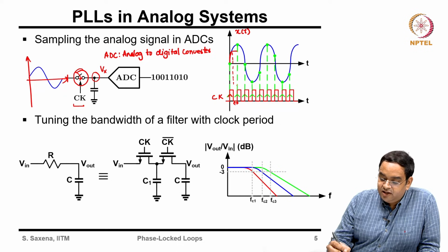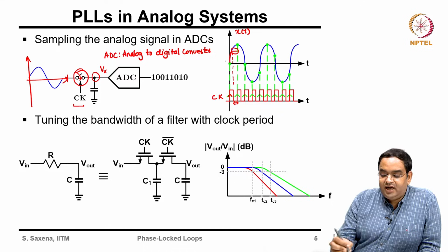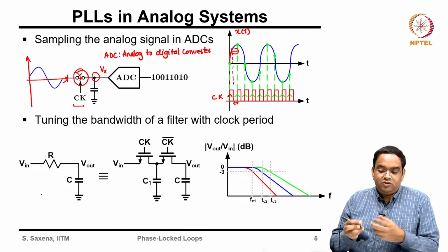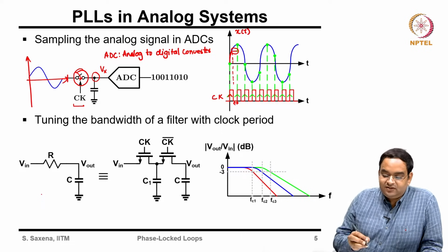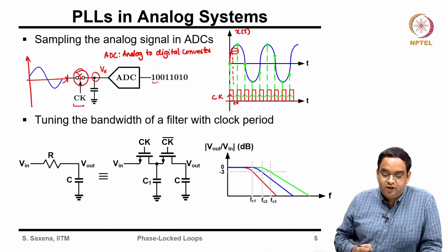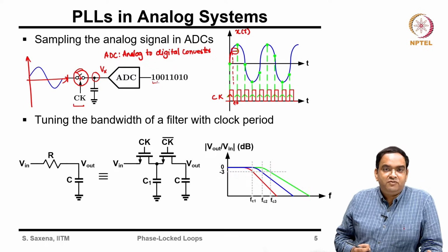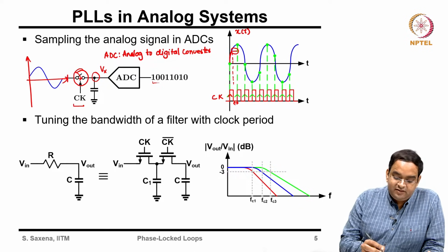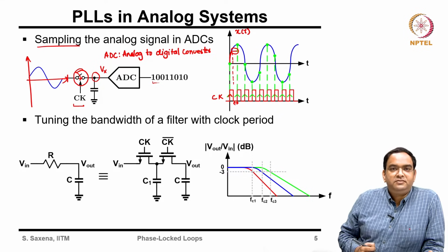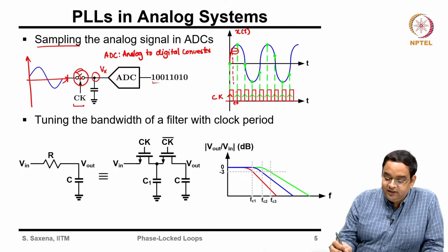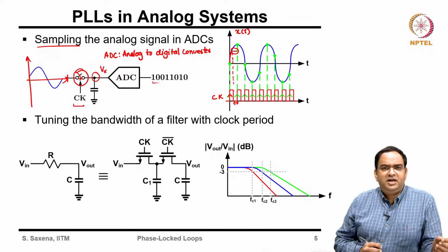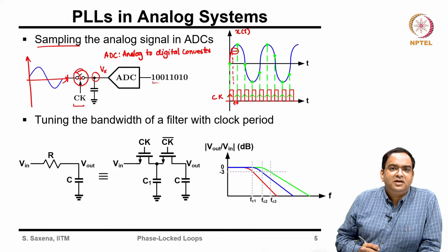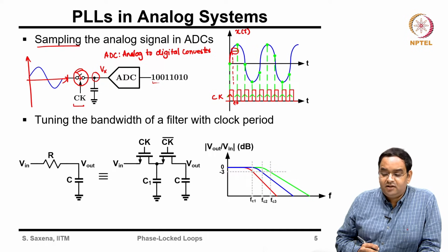Now, similarly, you are doing this. So, when you have this held voltage, you go and characterize this held voltage, and you say, okay, this voltage is equal to 110 something. You digitize the signal, and when you digitize the signal, you can represent it in terms of bits. So, a fundamental operation which lies behind the working of ADC is this sampling, sample the analog signal, and this analog signal is sampled at a fixed rate. It depends on what rate you want to sample it. It should be just greater than the Nyquist rate.